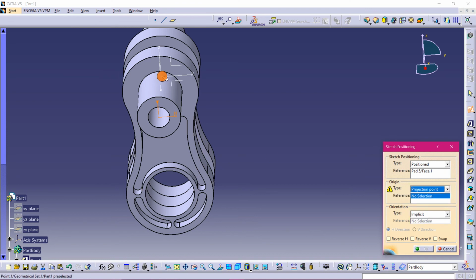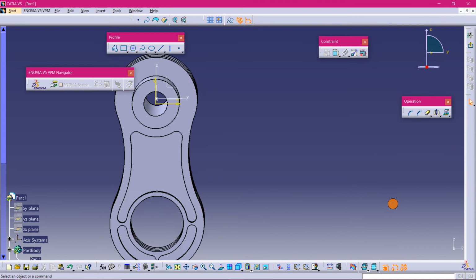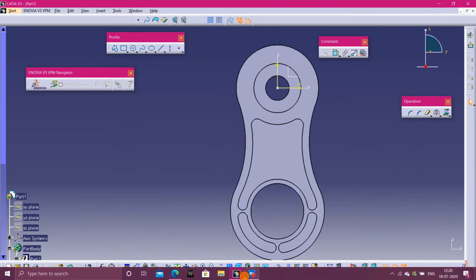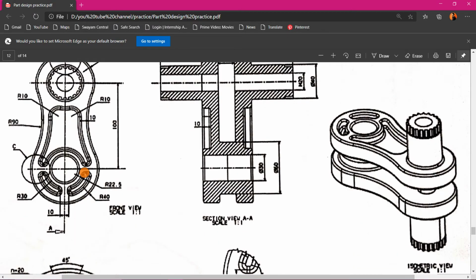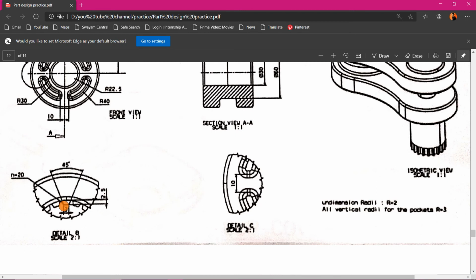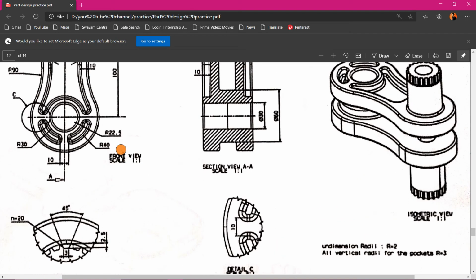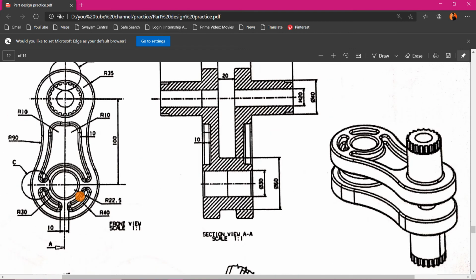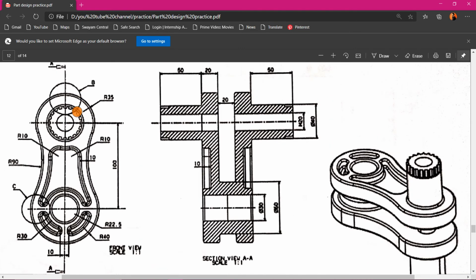See here, the angle between teeth is 45 and pitch is 3, height is 2.5. Okay, see, outside and inside. So I will be just first of all isolating this, and I will be drawing the inner circle.